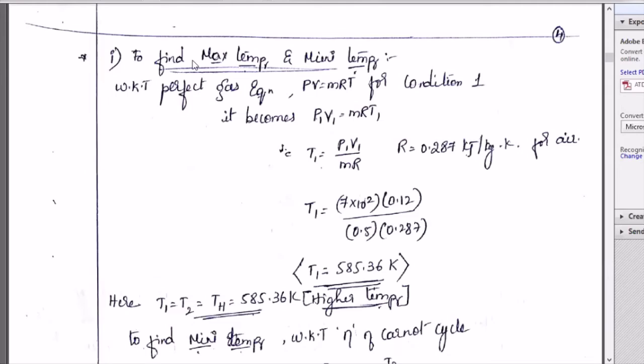For that, we don't have any formulas where it contains a temperature. Go for the first process, isothermal expansion. What was the first process, 1 to 2? Isothermal expansion. Q_S is equal to P1 V1 ln of V2 by V1, or m R T1 ln of V2 by V1. Using that equation I could have found it, but a little bit of data is not given in that.